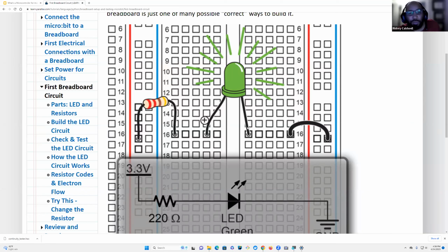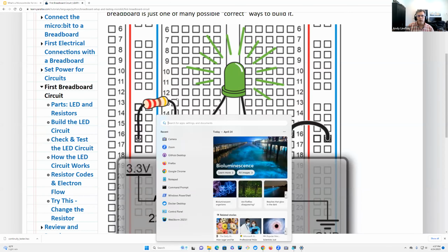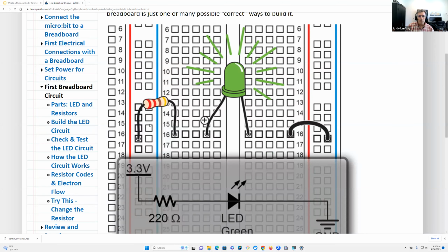Then an offline question would be, I'm looking for it, but I haven't found it: how much current can a particular pin supply? Yeah, so microbit pins are particularly wimpy. They don't supply a lot of current. Let me see if I can find my calculator. I see here 3 onboard peripheral. It says 90 milliamps or 300 milliamps max. Okay, so when you're on the supply like this, the microbit's regulator is 180 milliamps or something like that. I'll have to look that up.